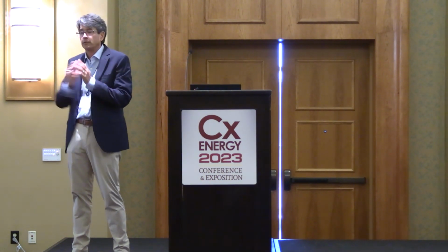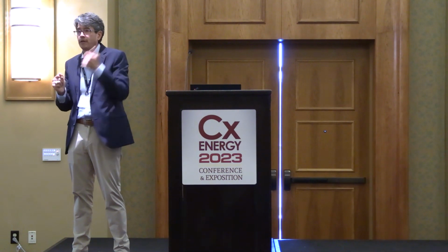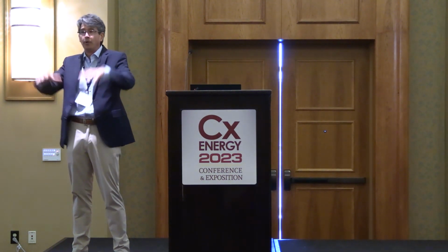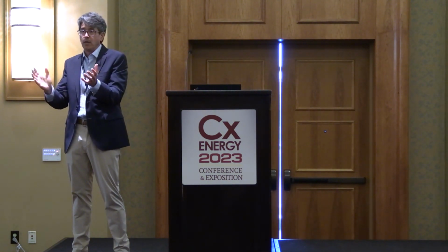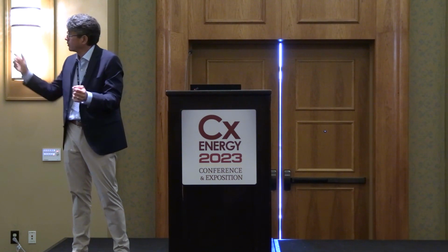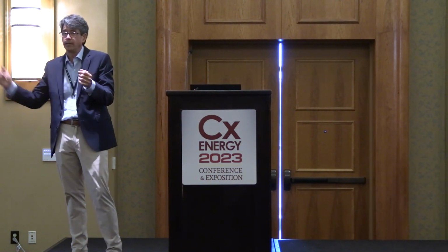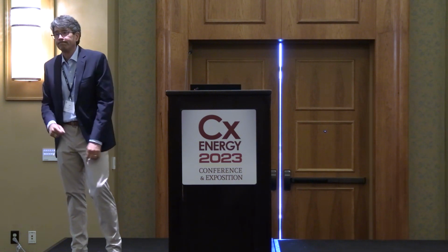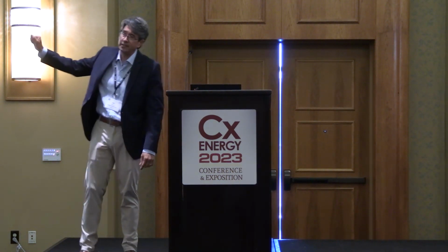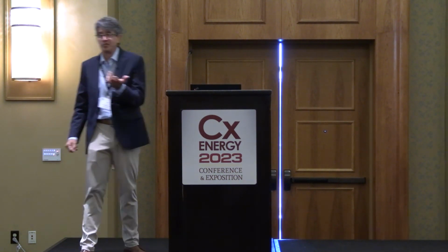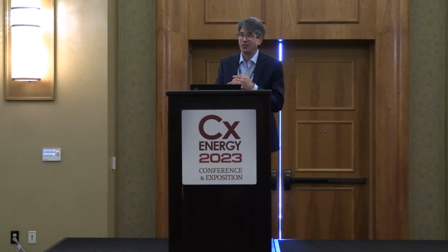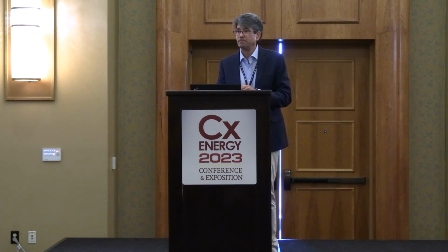I don't think those work. Hospital, six rooftops, Iowa, all faced north. It was wonderful on that side of it. Their building was bouncing all over the place. The day I went there, the hospital was incredibly negative. All the outdoor air dampers were closed, and I looked at the very first one. Thank goodness it was pouring down rain. They're all full of water. So one, not filtered, not protected, in a bad velocity profile, and exposed to the wind. Once the wind starts blowing on them, you have a big problem. Airflow monitor stations are fantastic, but we just need to make sure they get applied correctly.